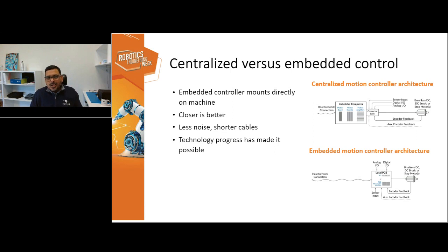So the common theme that comes in when they look at build versus buy is, do you want a centralized control or a distributed kind of control? If you take a robotic arm, you could put a controller right at each axis and just have power and communications, either CAN or Ethernet, go from axis to axis. The other approach you see, like the ABBs and the KUKAs of the world, is they have a huge central controller, and that computes everything and just sends PVT commands to each axis.